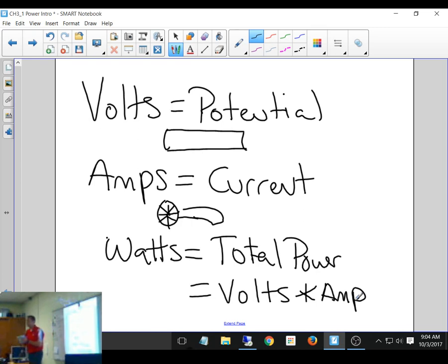Okay, we ground ourselves because it's all metal, but why is it really all metal? So it won't catch on fire. Because it won't catch on fire, and I talked about how last class we used all the power supply testers. We pulled the power supplies and we tested them so that you guys know how to test them. And I talked about one of my students who was working on a computer. He left the power supply connector plugged in, and he came to find me to tell me that the power supply was bad. When we returned to the classroom, there was fire inside and smoke billowing out. And if this wasn't metal, that would have caught something else on fire.